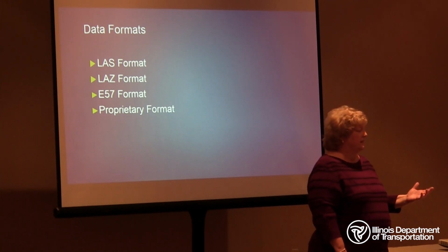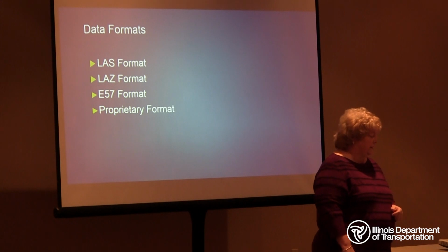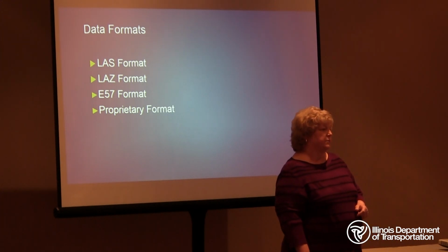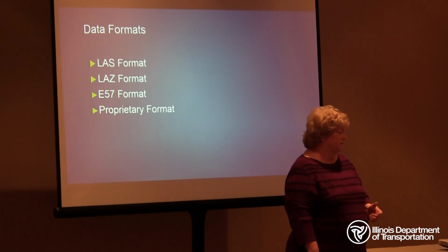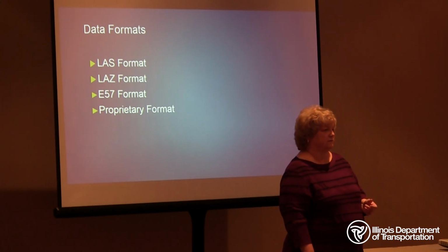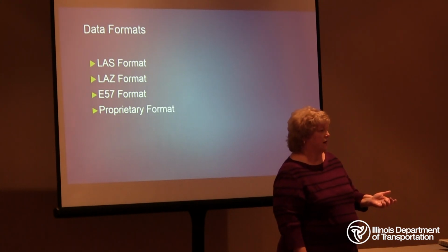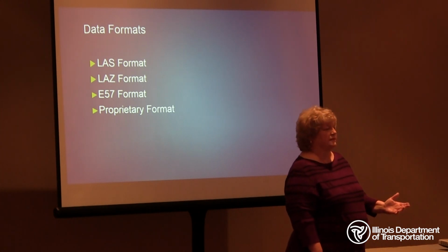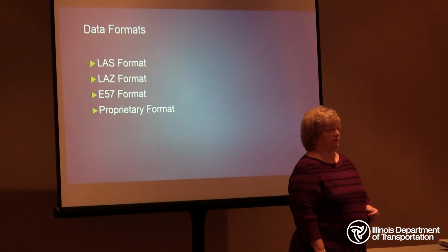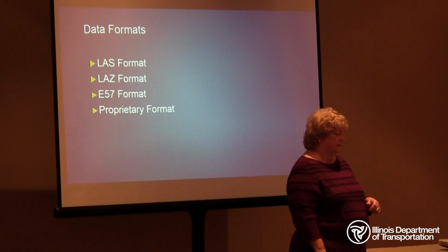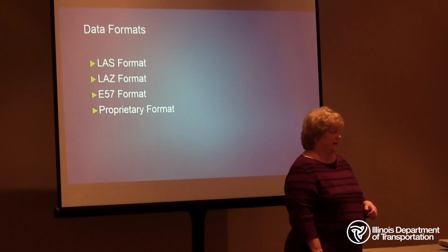Now the LAZ format is a compressed version of the LAS. It will be 10 to 20% smaller than the LAS files, and you can use software called LASzip to compress and uncompress it. It is good for backup and archives due to the smaller storage. But you cannot compress any LAS files that contain waveform data. It doesn't work.